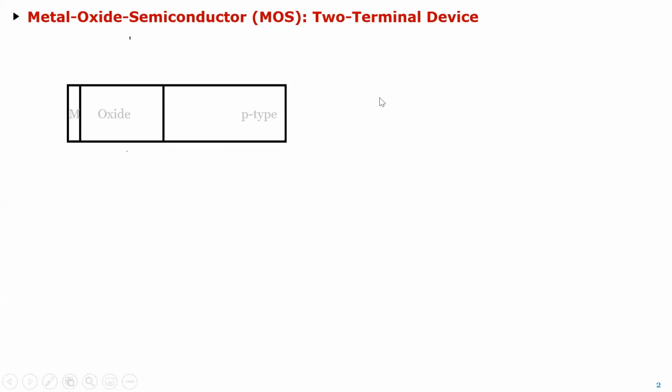All right, so I think I kind of explained this a little bit last time. So everything we talked about, we'll try to put together to go over the threshold voltage concept of MOS device. I gave you a sort of motivation last time. Why are we doing this? For obviously to do a switch. But before we do switch, I showed you, for example, a FET device controlling a depletion through a field effect. And we said that's not good for doing IC because the density is low. We need contacts on both sides and so on.